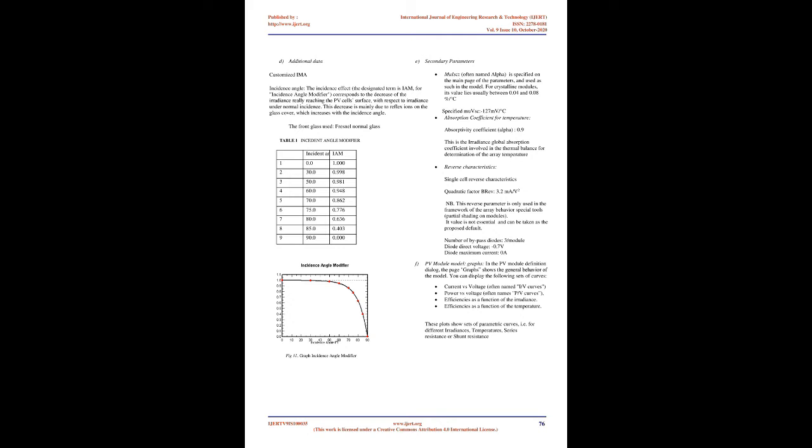In Rajasthan winter falls from October to March so tilt will be kept 47 degrees and from April to September it is kept 16 degrees. C. Configuration of the system. The simplified schematic diagram of the system is given below. The PV array is connected to a PV inverter which is then connected to a battery where the energy is stored. As shown in figure 3.